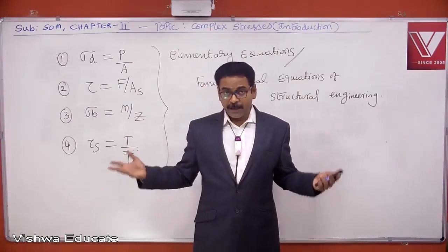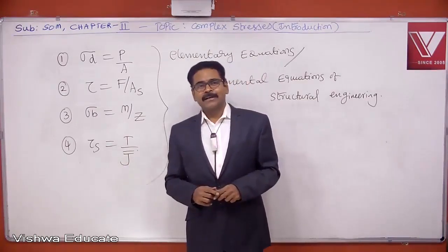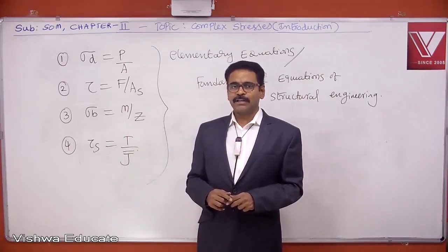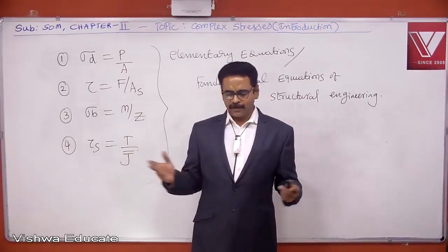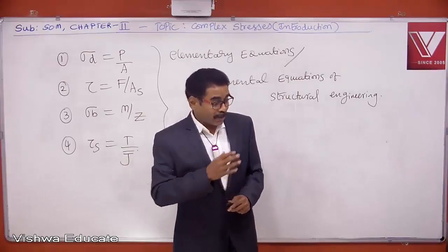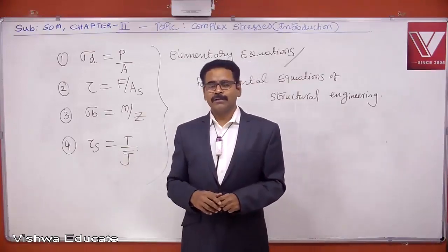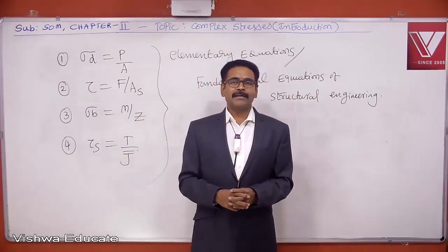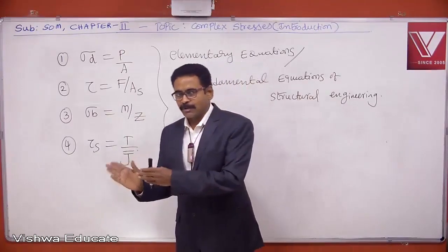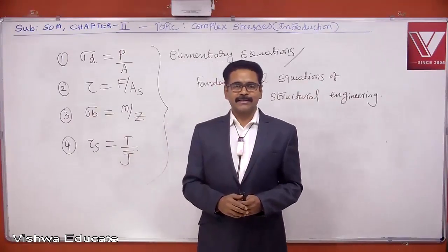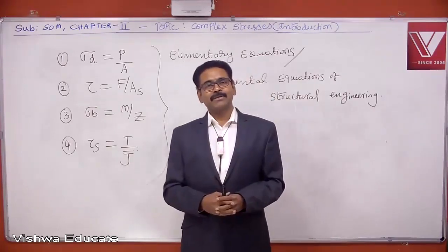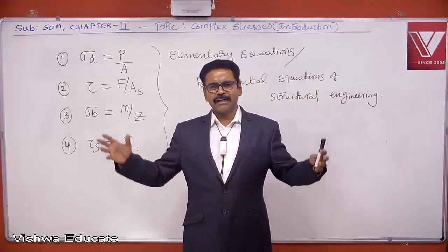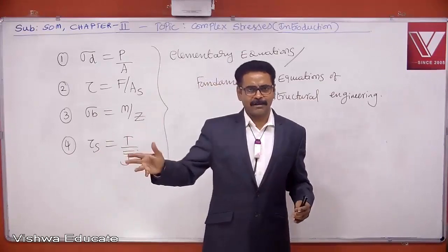Similarly, ductile structures fail about the shear plane. If I know the angle of the shear plane, I can observe that plane. If nothing is happening about that plane, nothing will happen to the entire structure. If the shear plane is safe in ductile structures, the entire structure will be safe. We need not blindly worry about every plane.